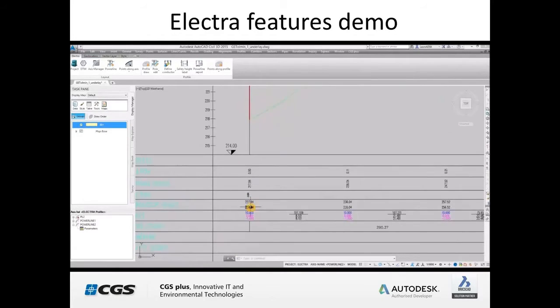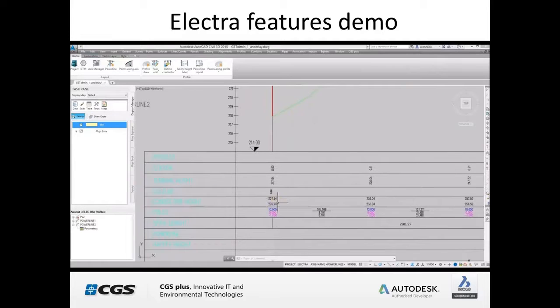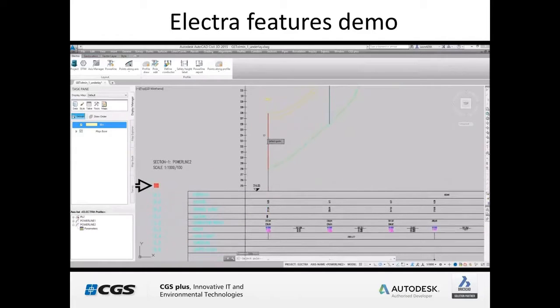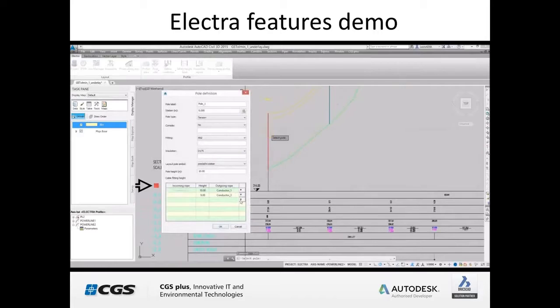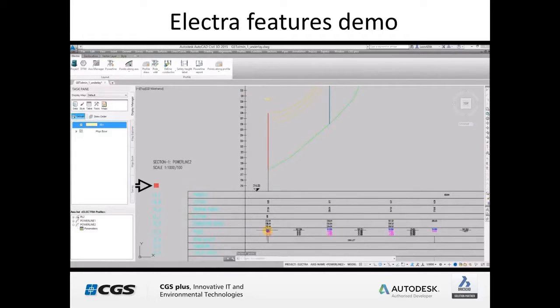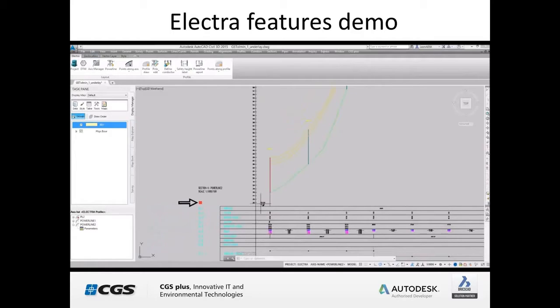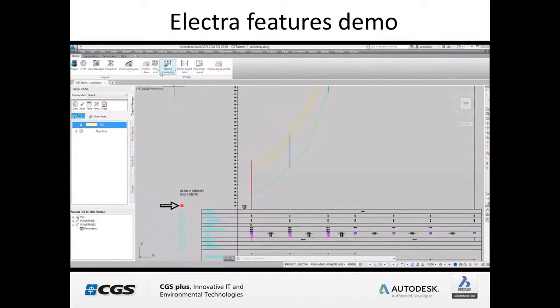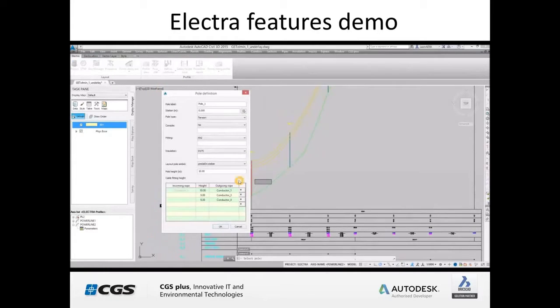And in the bottom you can see that the conductor's height and the poles' attaching point heights are represented, and bear in mind those values below. So we will now add an additional pole, and the height of those bands is limited now, and as we add a third conductor here, we'll put it on 8 meters, OK. So the bands are automatically updated, and also the height of those bands is automatically updated. So no need for users to edit those bands manually, adapt the heights, etc. So everything is basically done on the fly.